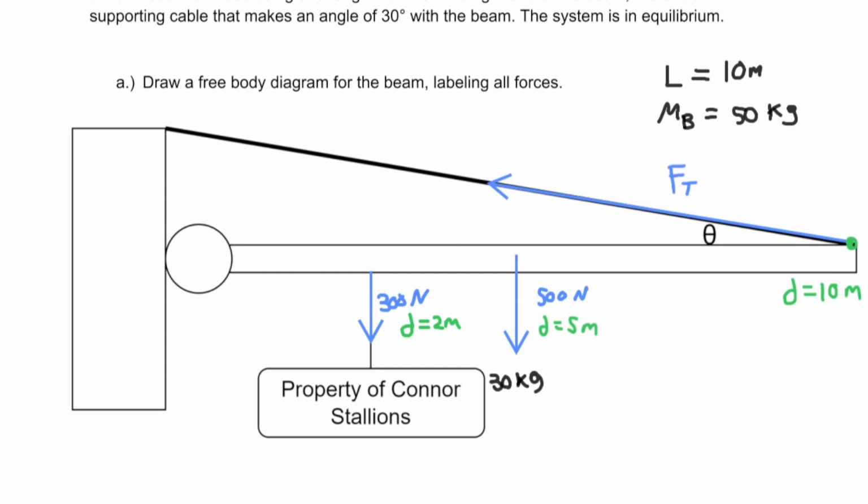And then the force that we always forget about, but is definitely still here, is there's always a force when two things are in contact. That's the normal force. So the beam is in contact with the wall at that point, so we're just going to draw in some direction a force caused by the beam, a normal force, a contact force, or it's commonly written as a hinge force. Again, I don't know if the direction of this is right or not. We may find out later. But I do know there is a force there. All right, quite a lot going on.